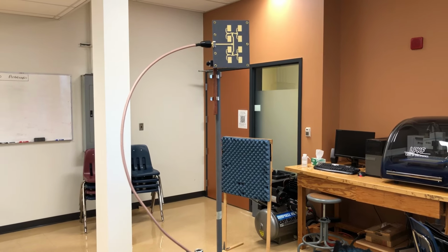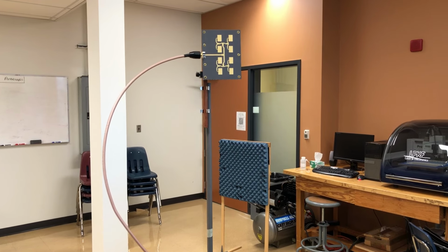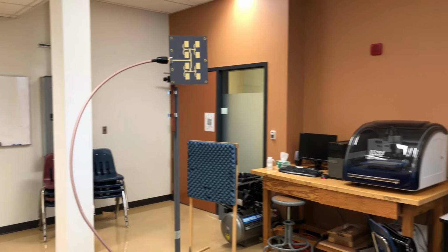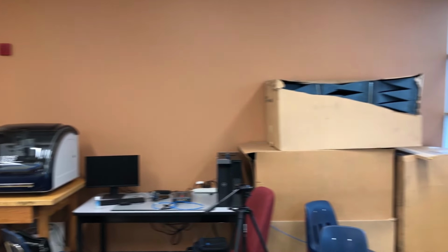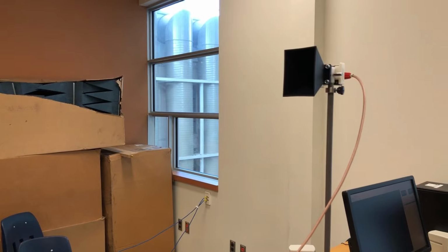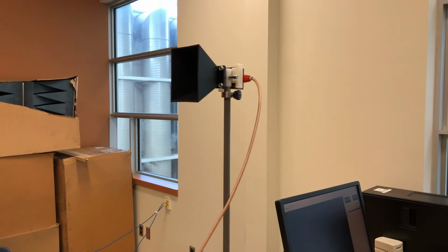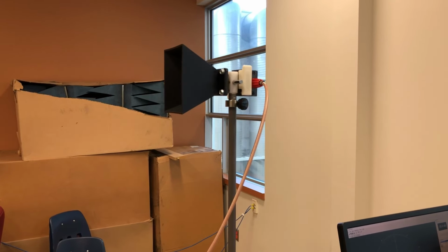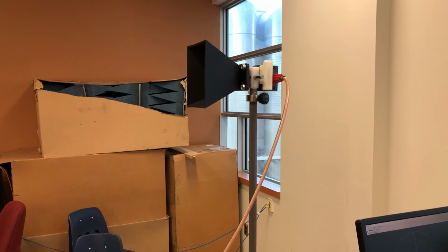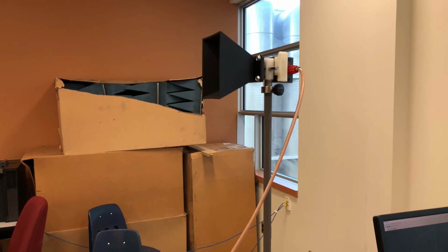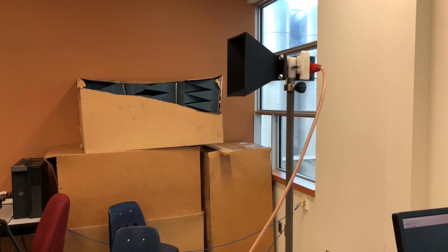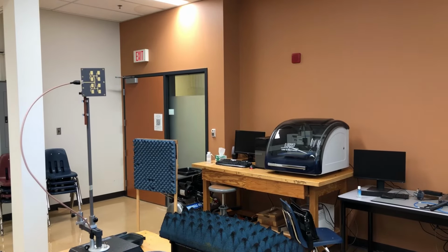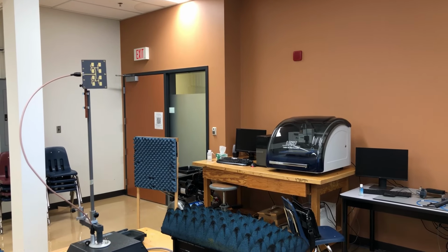So that's our E-plane. But as soon as we've rotated it, now the polarization is horizontal. So to handle that, we need to be able to provide horizontal polarization for this antenna to get the copole E-plane. To do that, if you look at the horn antenna that we have here, we've also rotated our horn antenna 90 degrees. So if you look at the waveguide adapter, you can realize that this is in fact horizontal polarization. The other one, I mean the receive antenna, is also expecting horizontal polarization. So I'm going to be collecting the E-plane cut using this setup, copole E-plane cut.